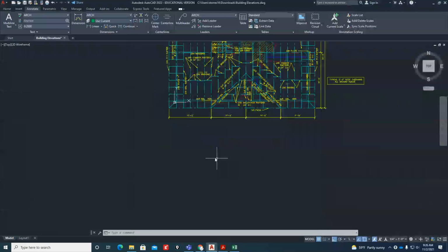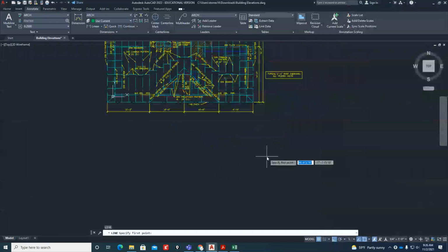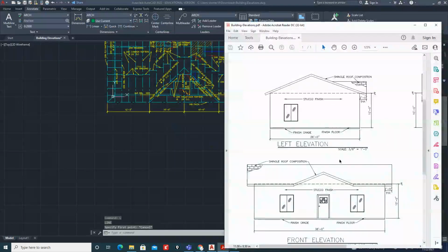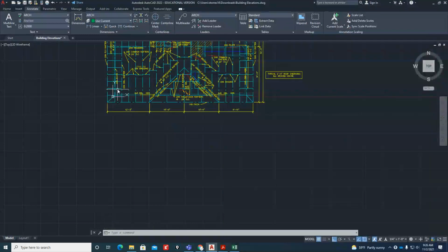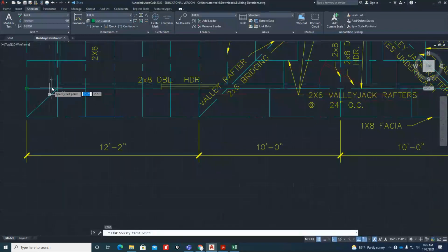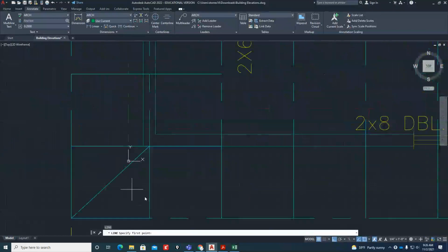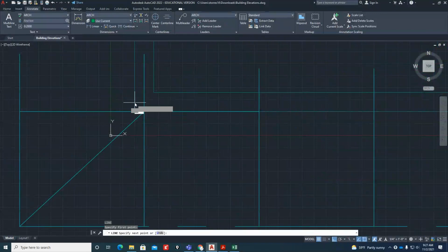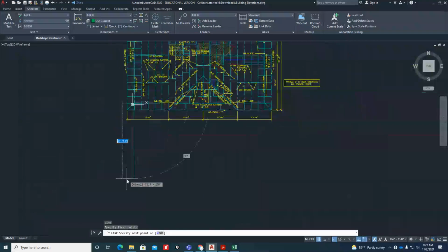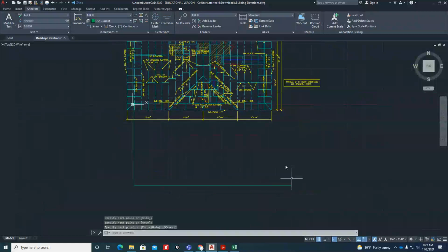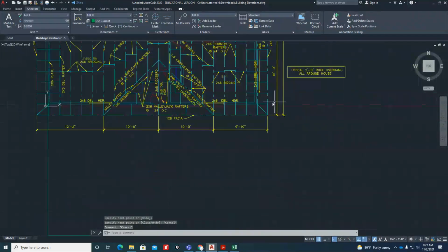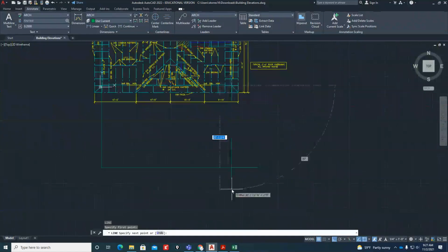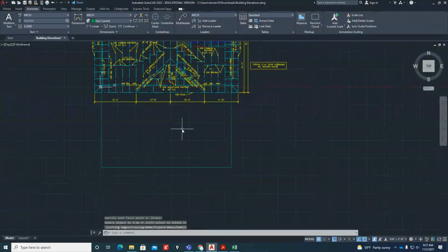Okay. As far as the object lines, I'm going to simply use my projection method. The width of the house, and the windows and doors, are going to be simply projected to the front of the house. So from here, I can just draw a line from the outside edge of the house. What is that green line? Oh, that's part of the grid. So it's actually the outside edge of the house. I'm going to take that line and project it straight down. I'm going to draw a generic line straight across to represent the finished floor, and then another line from the edge of the house, which is the wall, down to here, and then trim right there.